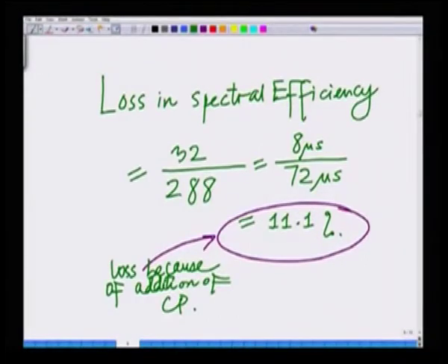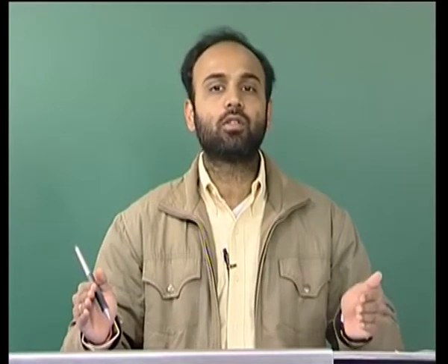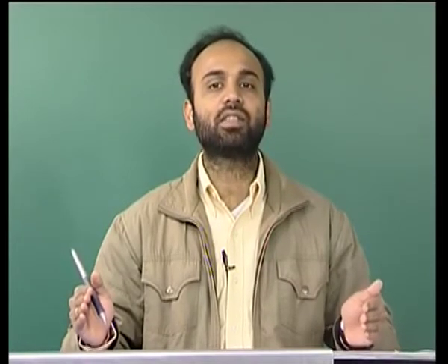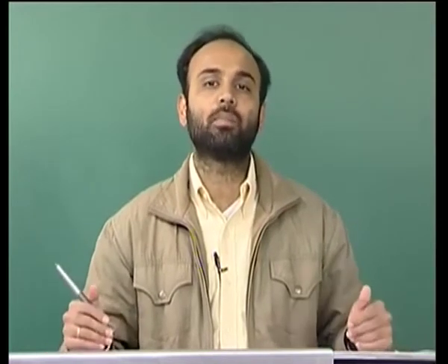OFDM. We talked about what OFDM is and the motivation behind OFDM. We introduced the multi-carrier modulation system, and then the implementation problems of multi-carrier modulation, and how OFDM essentially makes the implementation of such a system easier by the introduction of an IFFT at the transmitter and FFT at the receiver. And also we demonstrated the use of the cyclic prefix and how it removes the effects of inter OFDM symbol interference.